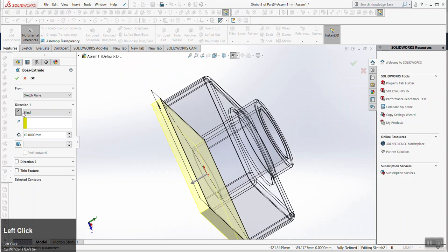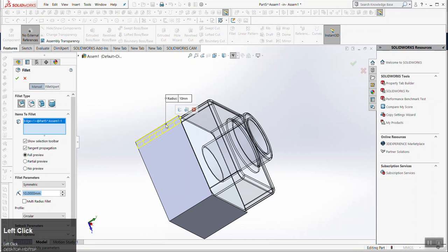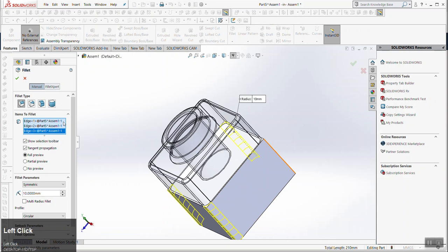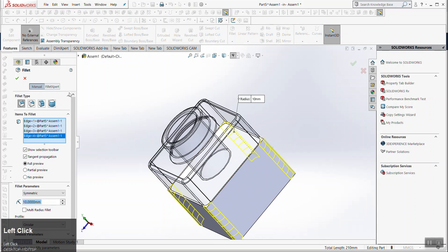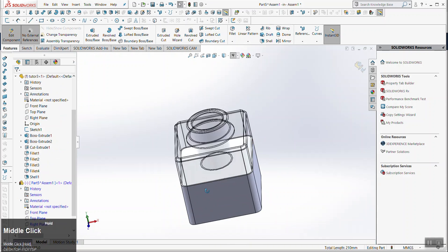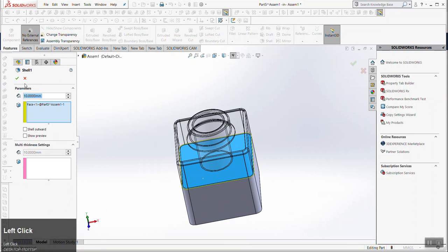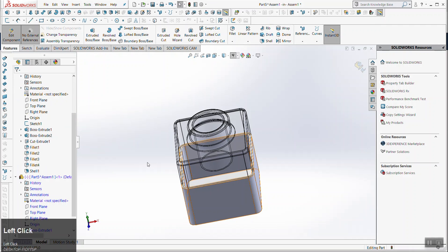It's a blind extrusion. It's 70 millimeters long. Same thing. I can apply fillets to it. I'm trying to fly through this because I realize I've been talking forever. The fillet defaults, I think, to whatever the last value was. But again, I can look at here. And just for the sake of simplifying this, I guess this is a 4 wall thickness shell.